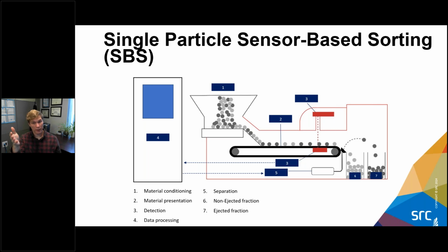So in this example, we would have a belt with air ejectors. There are going to be air ejectors spaced at intervals along that belt, with the idea being that when particles are moving along the belt, you can pick individual locations as they go over the ejector to actually eject stuff. And that's how you get those individual particles to separate.